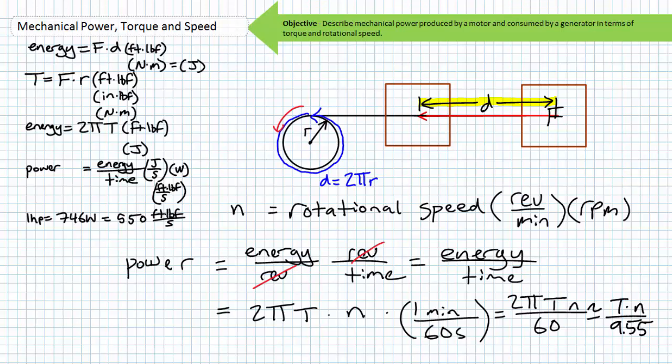There's a finite amount of energy that can be extracted from a physical phenomenon like falling water, expanding steam, or blowing wind. The more electrical power you try to extract from this phenomenon, the more the generator resists you and the more torque you need to apply to rotate at a given speed. Torque and speed must come into a generator for voltage and current to come out.